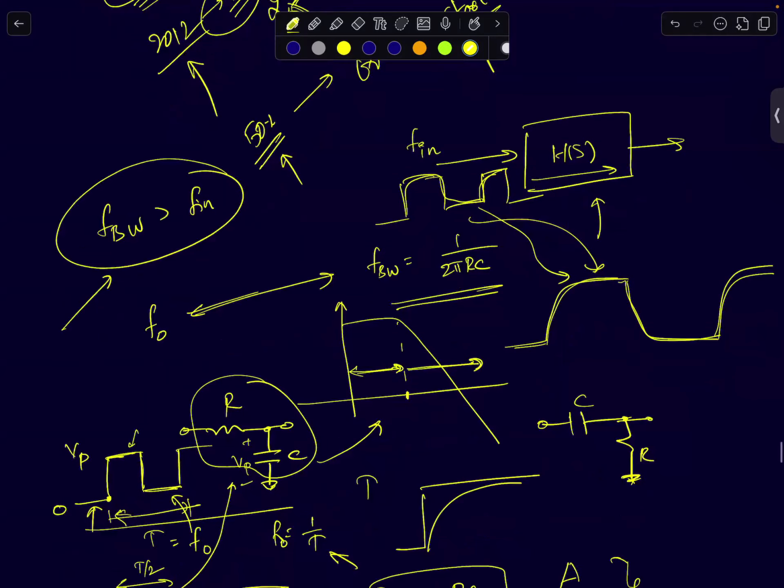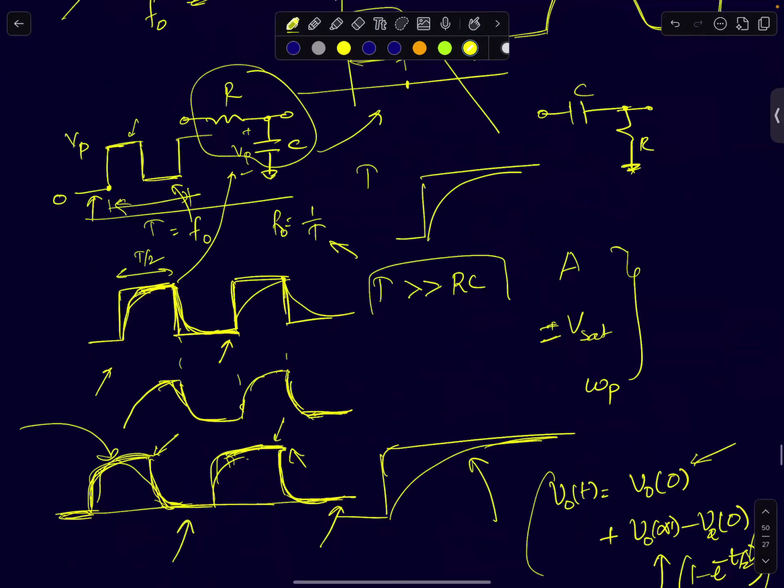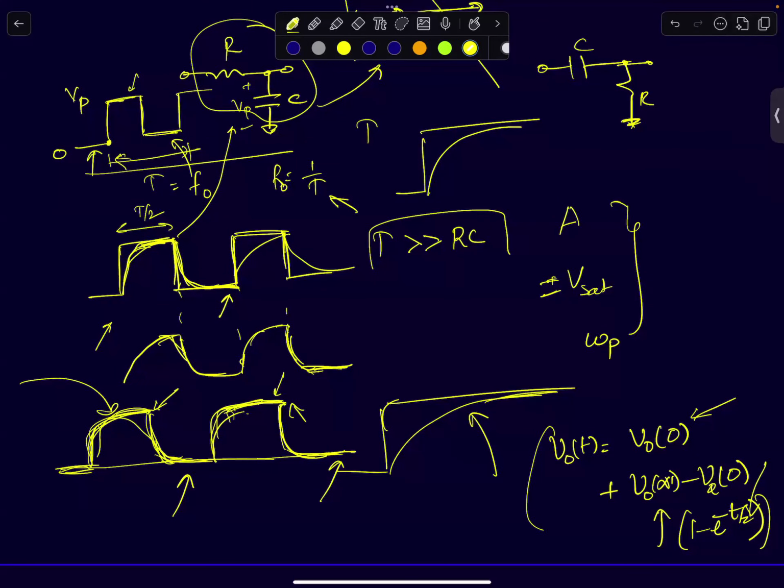So when you see a waveform like this, which is rising to its full value and falling back, rising to its full value and then falling back to zero, immediately you should know, okay, this is a high bandwidth system. So you don't have to worry that these systems may suffer much from problems like ISI. That's the understanding you gain by looking at this waveform.